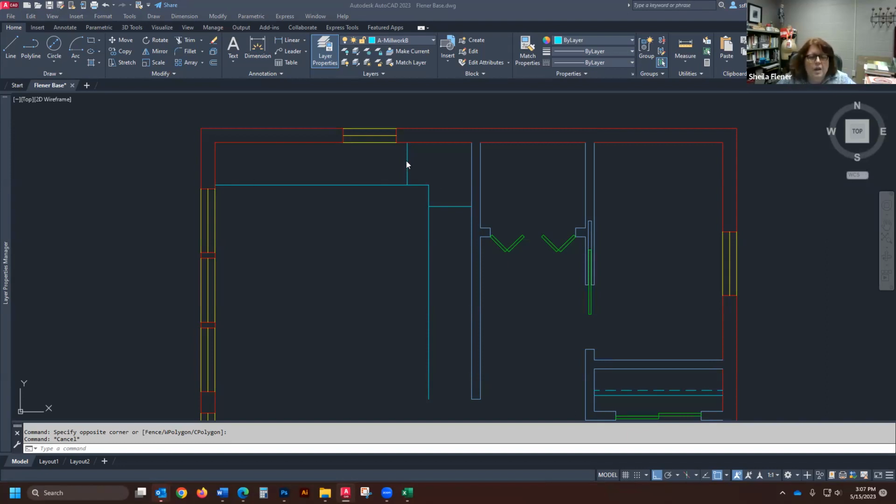Okay, so we're going to go on the window side and form the cabinets. So we're going to offset 42 inches for the sink cabinet. Then enter. Then we have a dishwasher beside the sink cabinet. So dishwasher is 24 inches. We'll click the line and go to the left. And then finally, we're going to put in a small 12-inch cabinet to put dishcloths and things like that.